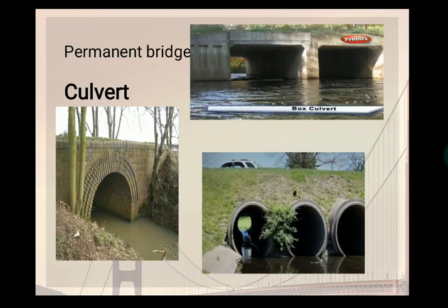Pipe culvert. For a very small drainage, pipe culverts may be used. It may have one pipe or more than one pipe placed side by side below the embankment of the road or railway. The pipes may be wooden, steel, RCC, cast iron, etc. to retain the embankment in its proper position and protect the pipe from the action of spring water.